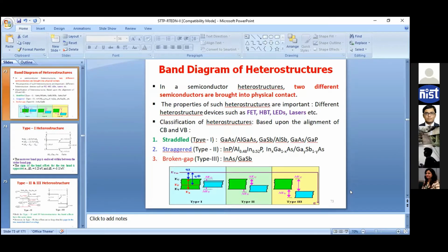Please, if you are aiming to make any device using graphene, then there is no need to make a semiconductor and graphene junction, because graphene is there, and we are trying to replace semiconductor with graphene. We can dope graphene itself to make it n-type and p-type. We can make a graphene junction itself. So people always try to avoid these kinds of devices like graphene-semiconductor junctions.